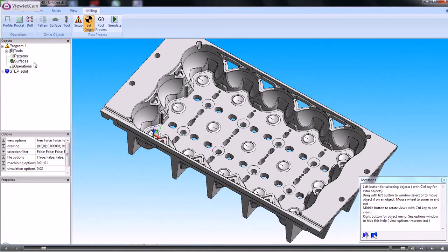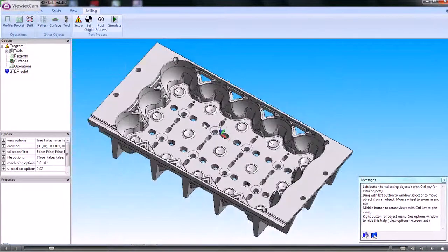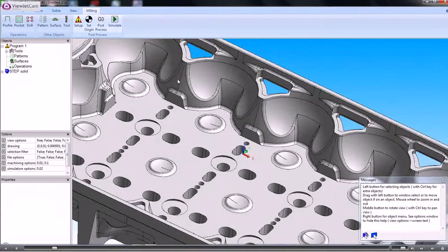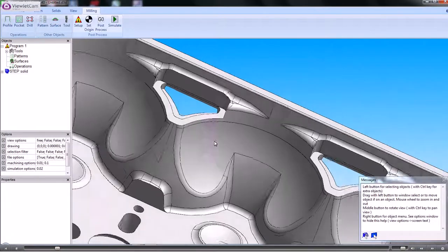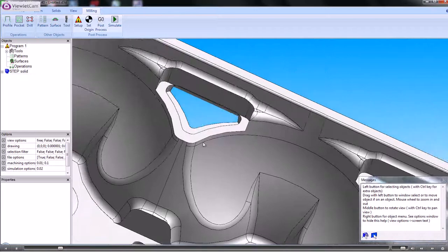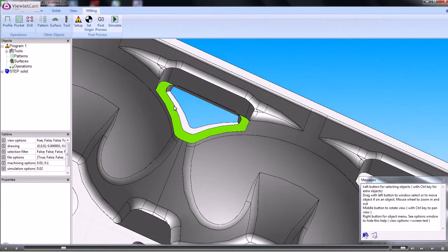It's always best to have the top of the file as the Z0 so that the dimensions in Z are measured negative into the workpiece. Okay, so that's the file there, and we need to machine just these pads here. Now if we wanted to machine those and select faces, what would happen is if we selected that face, that would give us an enclosed shape which wouldn't be what we wanted to machine.